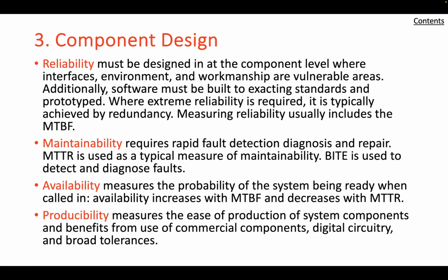Some of the measures that are used to enhance producibility are, and I'll just quickly go through these: maximum use of commercially available parts, setting dimensional tolerances of mechanical parts well within normal precision, design of subassemblies for automatic manufacture and test, maximum use of stamping, casting, and other forms of suitable high rate production, use of easily formed or machined materials, maximize standards of subassemblies, and maximize use of digital versus analog circuits.